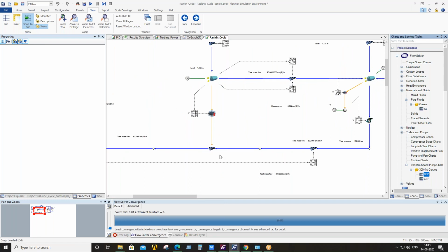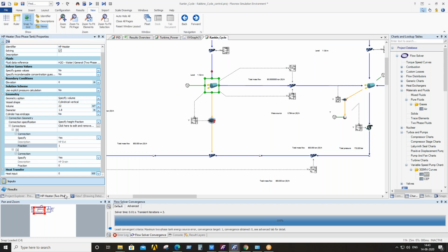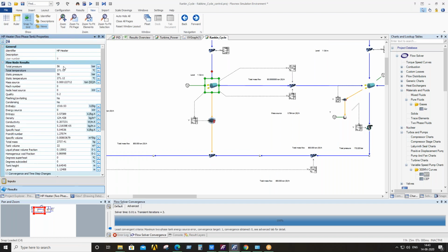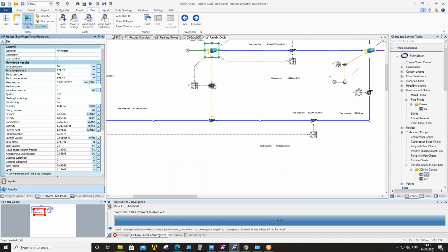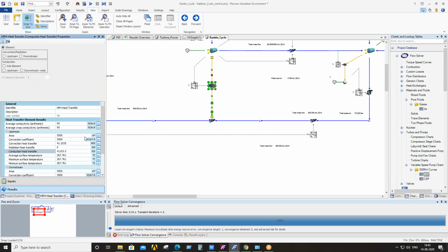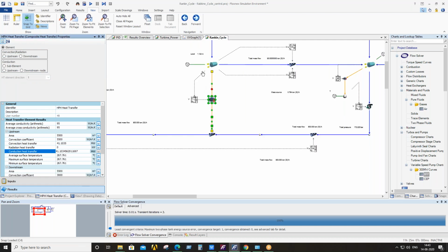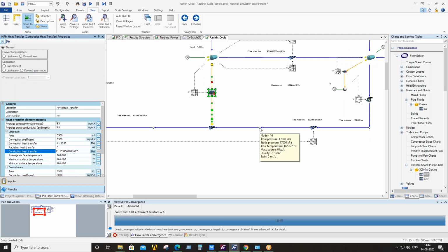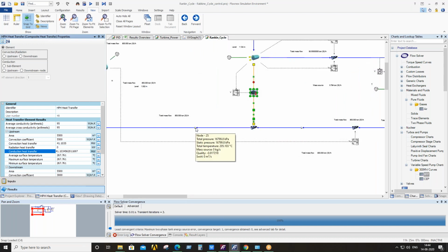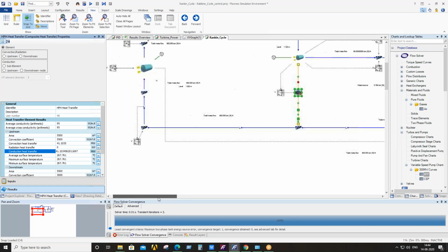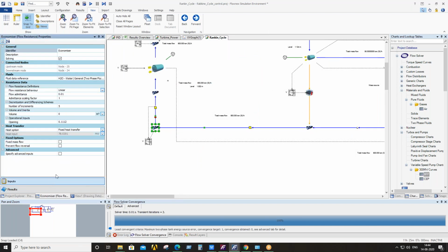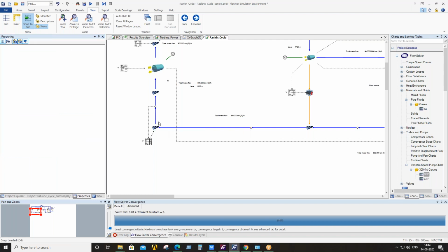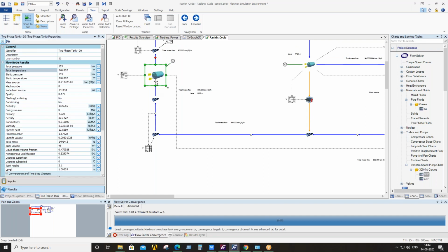Here it again gains heat in the HP heaters. The HP heaters are maintained at 56 bar and a temperature of 271 degrees Celsius. Around 41 megawatt of heat is extracted from the HP heaters, so that the temperature of the feed water increases from 162.62 to 205 degrees Celsius. This feed water again goes to the economizer, where we give the heat input so that the temperature of the fluid is further increased up to 280 degrees Celsius, and this fluid goes to the boiler.